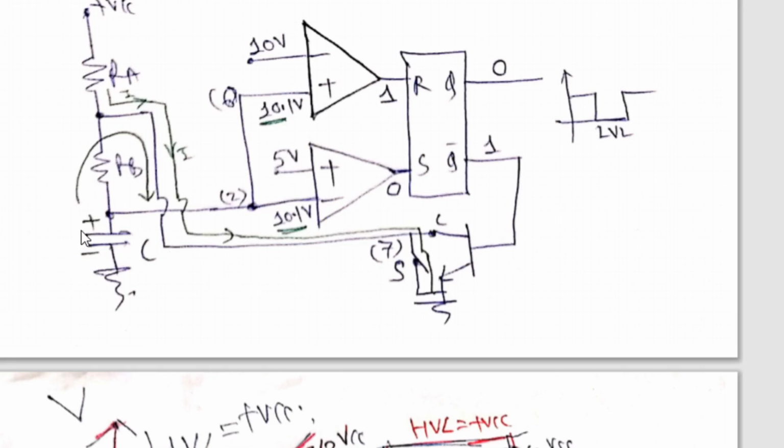Number two, the capacitor which was already charged to two-third of Vcc, that is just about 10 volt, gets discharged. So see this arrow, that capacitor gets discharged through Rb. Why? Because this terminal is connected to the ground. Therefore, this is the discharge path of the capacitor. Whenever we short circuit the capacitor directly or through a resistor Rb, capacitor gets discharged. And in this way, when transistor is forced into closed switch, the discharging action of the capacitor starts.